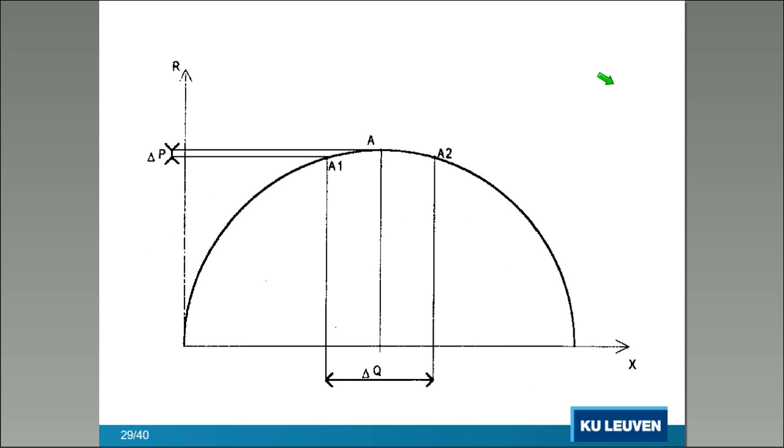I will not go into the details, but on the horizontal axis, you have reactive power of the system. On the vertical axis, you have active power, so the heat in the arc, let's say. Where is the working point of our system? Let's say it's not completely true, but it's a good approximation here on top of this circle.